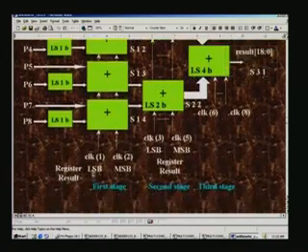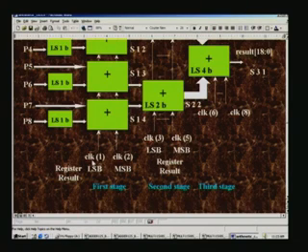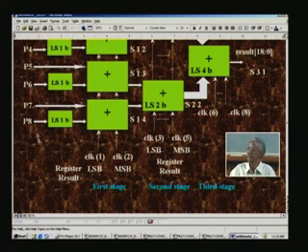And in fact if you see the clock, we have the very first clock. In fact, the very first clock will register this P1 through P8, and then N0 and N1 are the actual inputs that will be registered first, followed by this register. Only with the arrival of the next clock pulse do we reckon it as the first clock in order to do the internal processing, and we need 1 through 8 clock pulses.